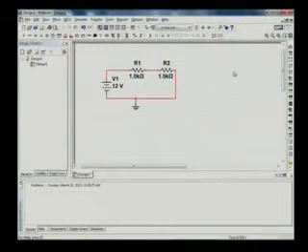By Kirchhoff's voltage law, if I am applying 12 volts, the voltage across R1 should be 6 and the voltage across R2 should be 6, because the algebraic sum should be equal to 0, right?